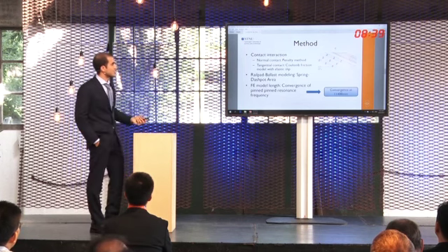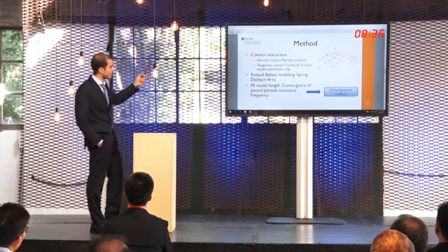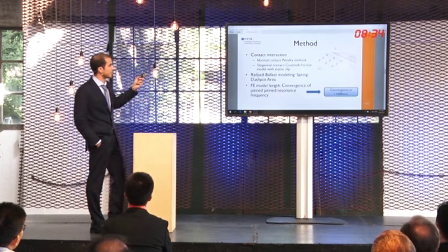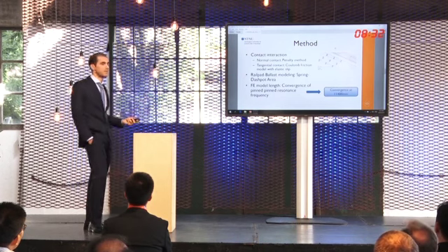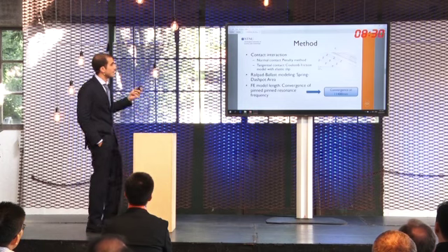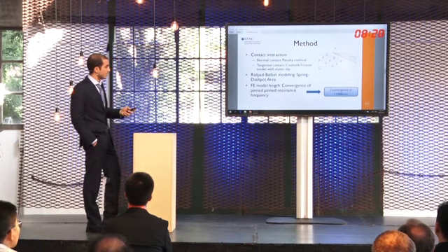For what regards the contact interaction in our finite element model, everything is basically standard. We have used a penalty method as normal contact, while the tangential contact is considered through a Coulomb friction model with a certain elastic slip.